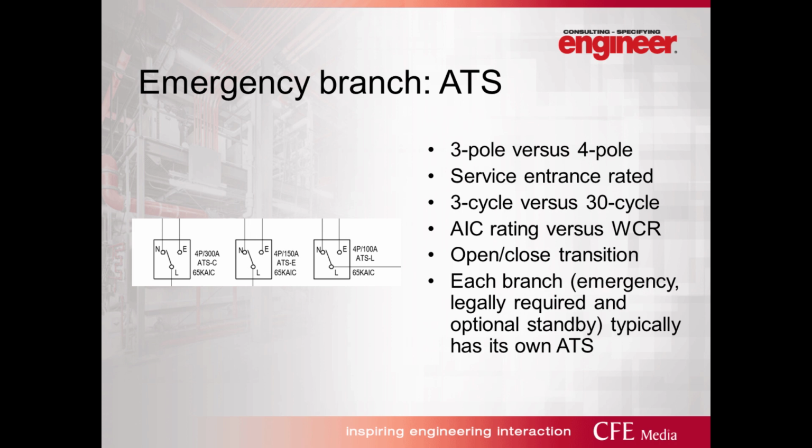Open versus closed transition ATS. Closed transition ATS is typically used in critical facilities. The open transition transfer switches are more cost effective. The closed transition might be required in healthcare facilities and data centers where the customer would prefer to avoid that split second changeover in power.